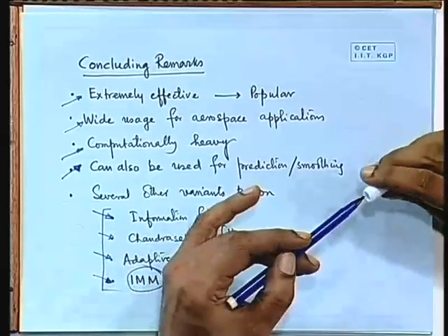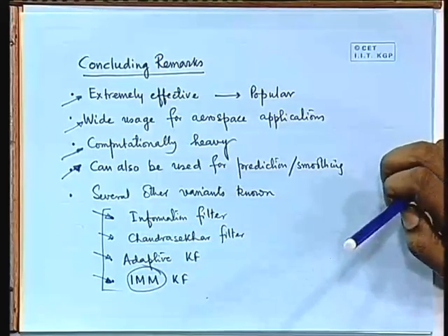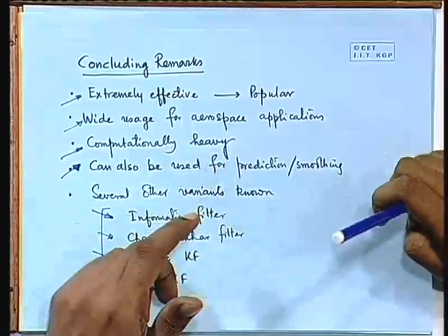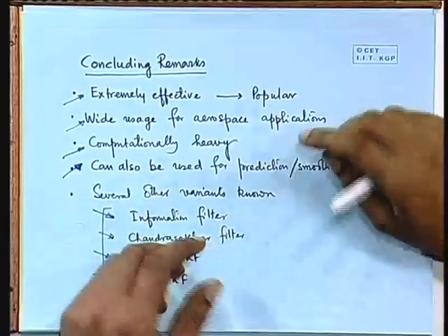These are typically used especially for maneuvering targets. Suppose you are trying to design a guidance system for a missile chasing an aircraft. The pilot is not going to sit pretty, knowing that a missile is chasing it, because it will also detect it. It's a cat and mouse game. So it will do maneuvering. It will turn right, left, go up, down, accelerate, decelerate, trying to evade the missile. From the point of view of the missile, you have a target whose acceleration level will be unknown and suddenly changing. So if you want to estimate its state, you have to use different filters. You can't get very good results by using the same filter with one Q. So for such situations, you sometimes use interactive multiple model filters.